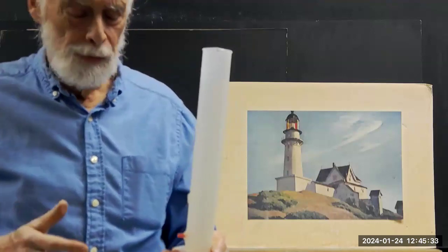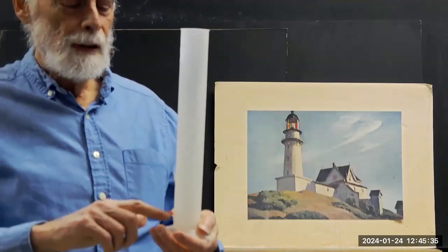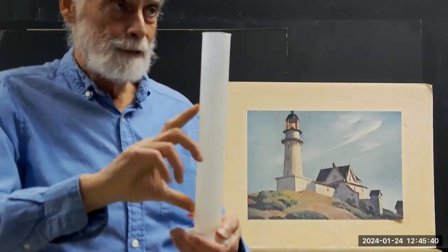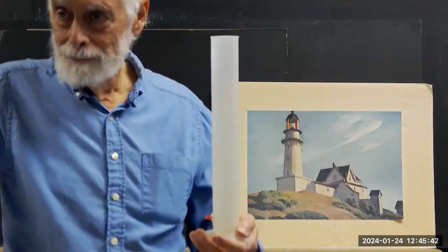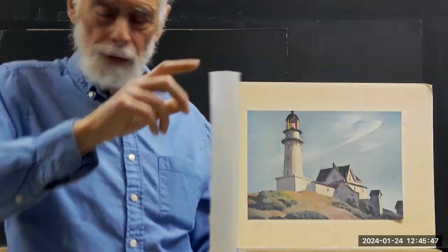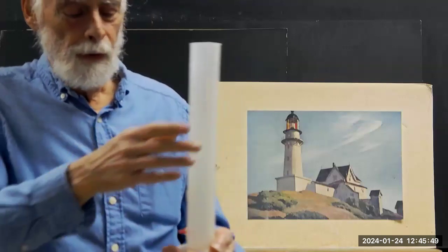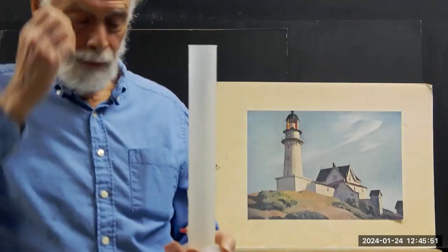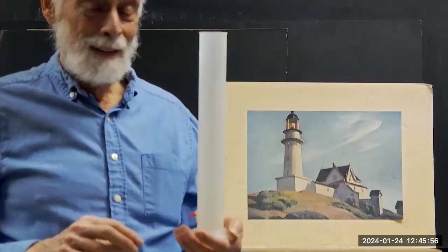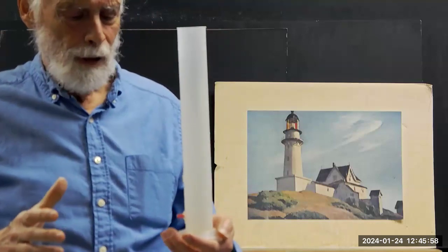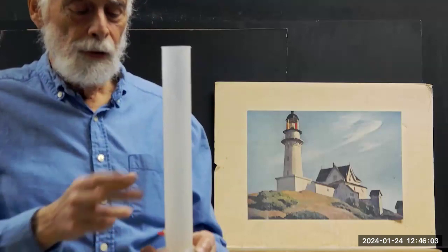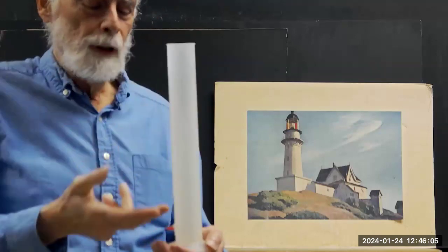This is in response to the question I asked: how much force does it take to support this water? Well, it's the weight of the water. You get the weight by measuring the distance and the diameter, you get the volume, and with the density of water you can figure out the weight. Then I asked, how does the water down here support the water up here? It's not totally obvious, but it's the pressure. It's the pressure down here that supports the water up here. So if we know the weight of the water up here, we get the pressure down here.